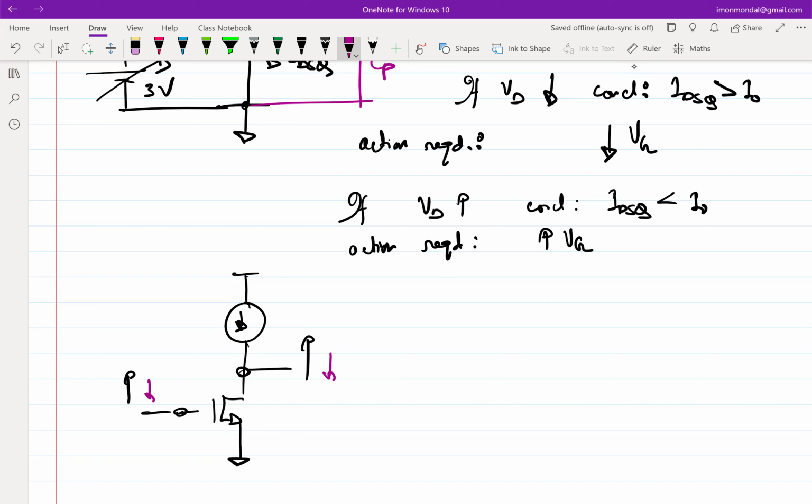So what is the easiest way to do that? Simply connect the gate and the drain. Okay, so firstly, this is what a logical thought process has led to, but it's not necessary that the intuitive logical thought process will always give you the exact answer, right? We have to go ahead and figure out whether this transistor is indeed biased in saturation, using analysis. So what do you think? Is your transistor in saturation?